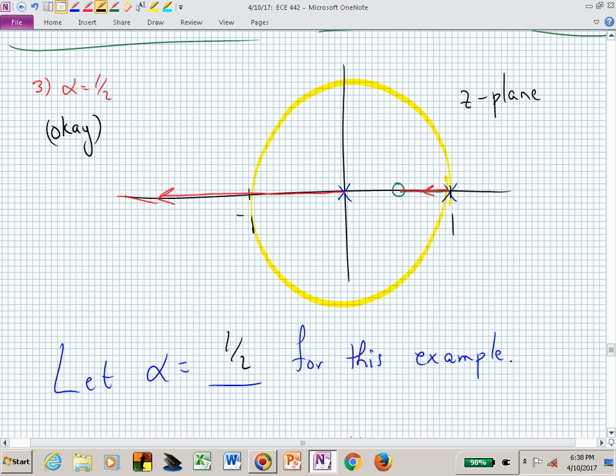What's the gain required to get me to z equal to 1/2 for that pole between 1/2 and 1? Infinite. I've now cranked up my gain k to infinity. What happens to the pole at the origin? Oh, brother. It's gone off to -infinity, so I'm way past this being closed loop stable.